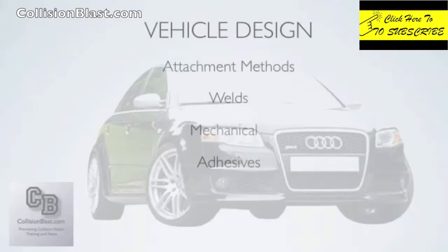So how are these cars held together? Now, we mentioned a spot weld, and that's the majority of the welds, but there's also some laser welds, which are done by machine. There are also some mechanical ways cars are held together, and this can be with nuts, bolts, rivets. And also, there's a lot of adhesives being used. There are some benefits to adhesives because it helps seal out the moisture.